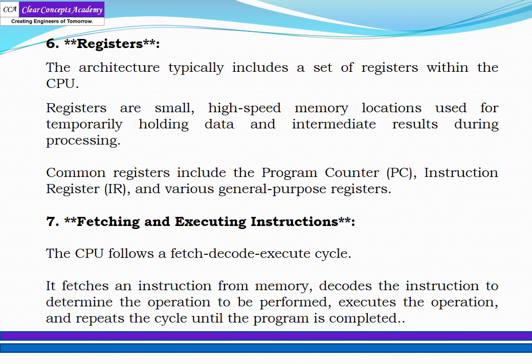That means one instruction will be fetched, it will be decoded and it will be seen what is to be done, add, multiply, subtract, whatever that is, and on which memory locations. Then from those memory locations the data will be brought, it will be operated on, and once this execution is completed, the next instruction will be called.